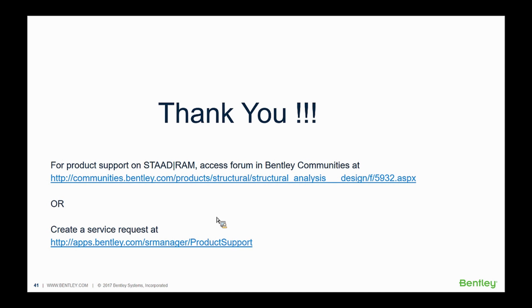The question is, I did not know it will give you story shear with base shear. Yes, it will give you the story shear with the base shear. Just ensure that you use a set command in the file called SET PRINT 17. And once you receive the file, you will see that set command right at the top. That actually prints out a few extra things besides the usual output, and so you can definitely get that story shear reported as part of the analysis output file.